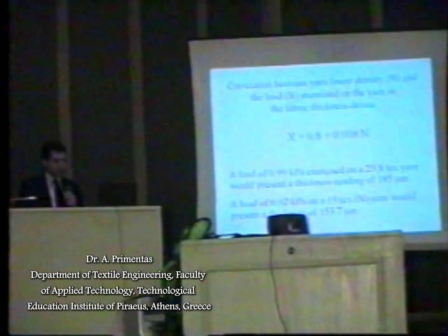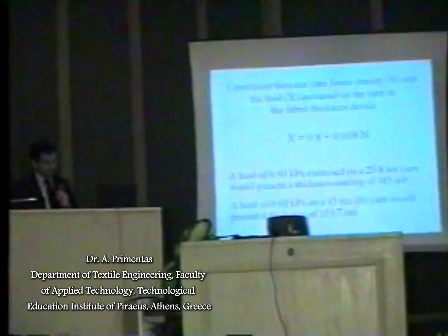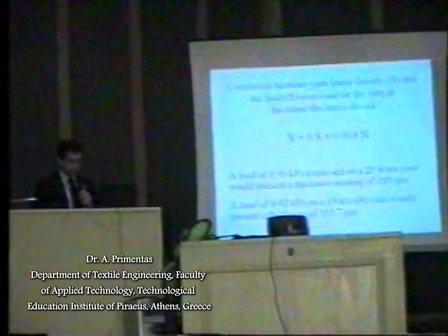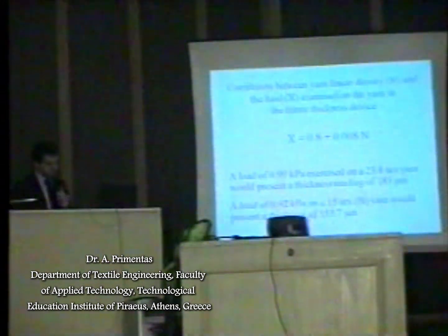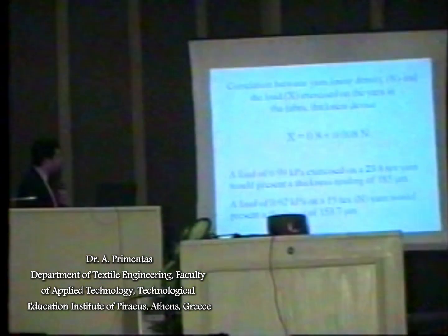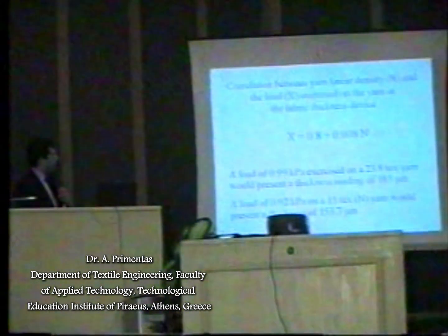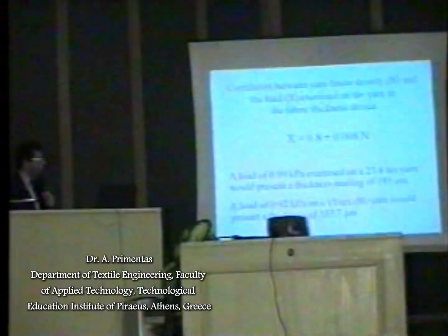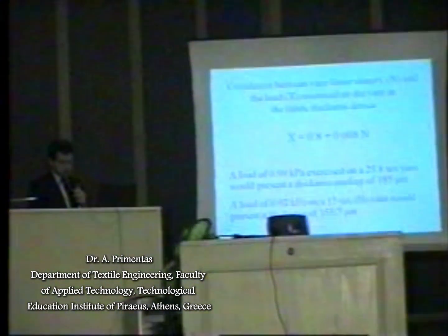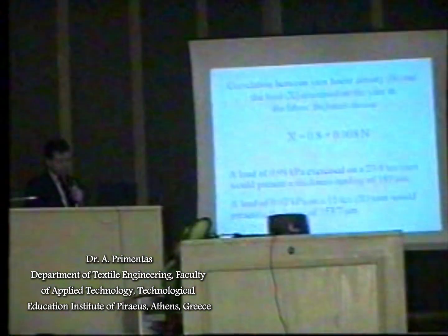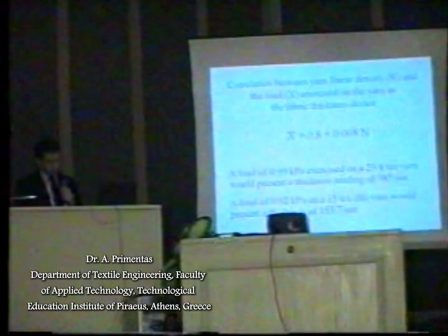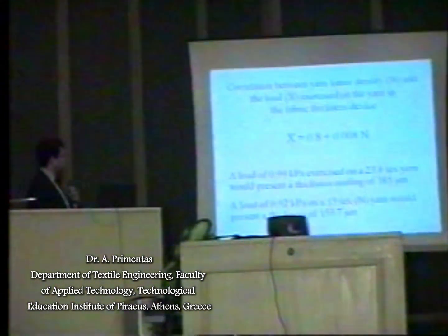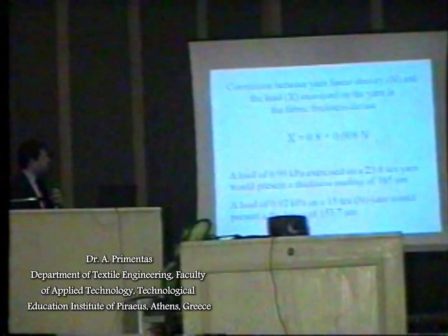On the other hand, the correlation between yarn linear density and the load, X, exercised on the yarn in the fabric thickness device was expressed with the following derived linear regression equation. Thus, the load of 0.99 kilopascal exercised on the 33.8 tex yarn would present a thickness reading of about 185 micrometers. Similarly, this load of 0.92 kilopascal on a 15 tex yarn would present a thickness of 153.7 micrometers.